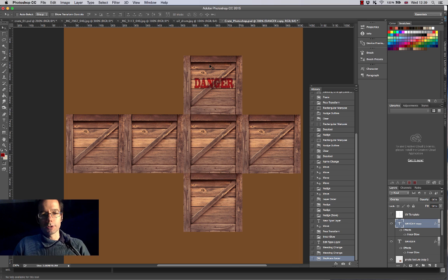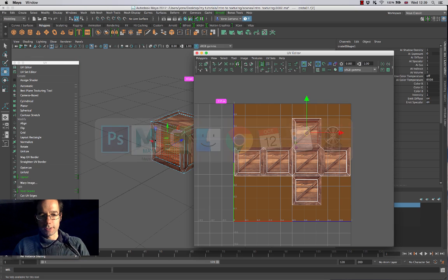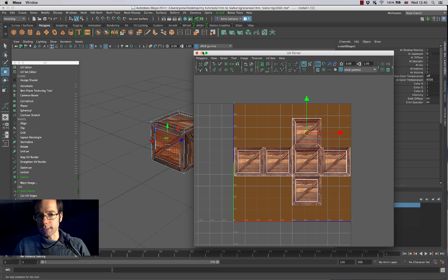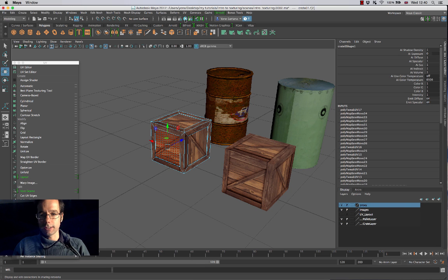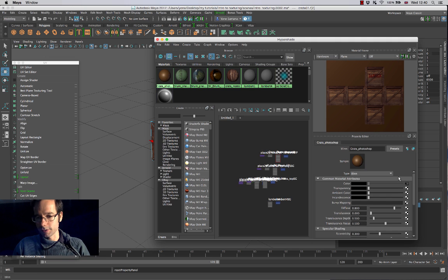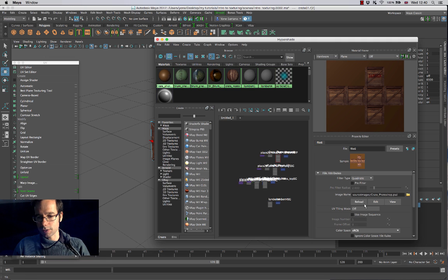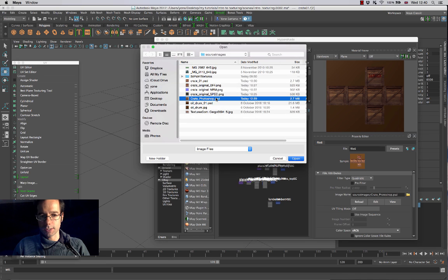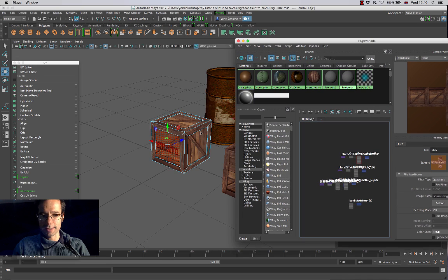And again, I'm going to basically go and save this file out now. And hopefully the text should appear in Maya when I reload it. So I'm going to come over here, come back into the Hypershade, and again, because of this little bug that I'm having over here, instead of using the reload button, I'm actually going to have to come into the file node over here, and I'm going to have to open it one more time. So I'm just going to hit create Photoshop. But again, this should just be the click of a button.